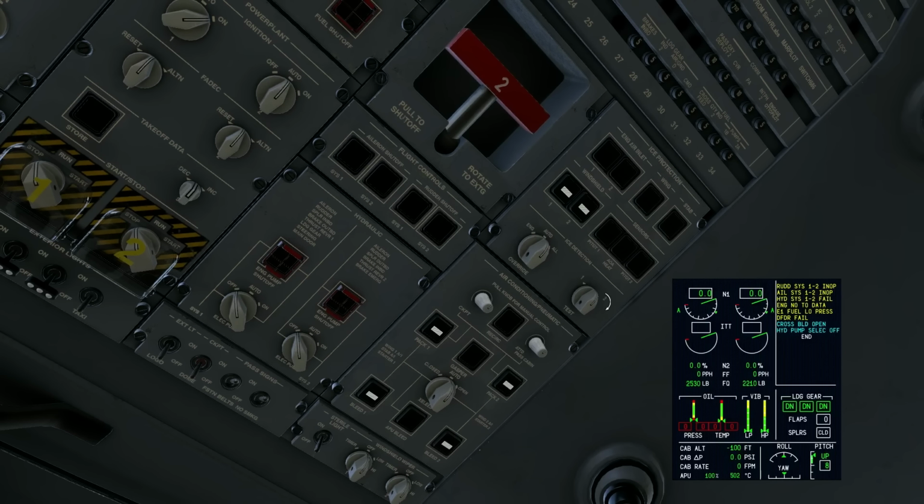Moving on over to our ice protection system. We'll go over this a little more once our engine's started so we can see it start moving. There are 2 different types of ice protection we have on the airplane. We have pneumatic ice protection on the top row and electric ice protection on the bottom. The electrics are a little easier, so we'll start with those. They are our windshields and our sensors. So pitot, AOA, pitot 2.